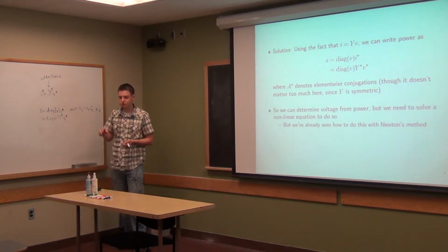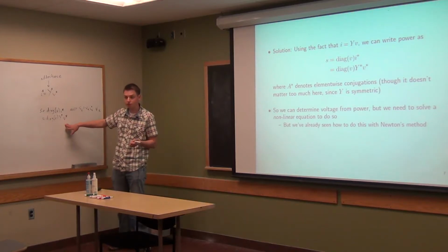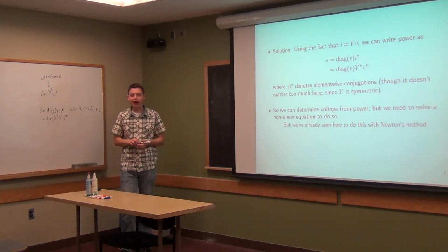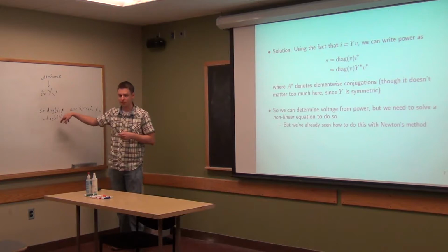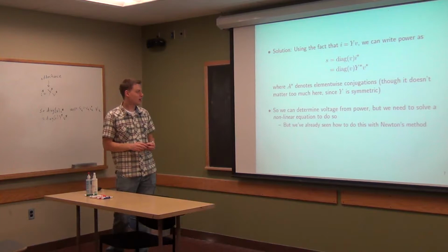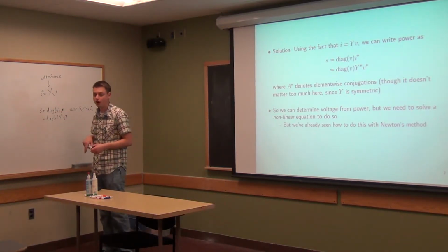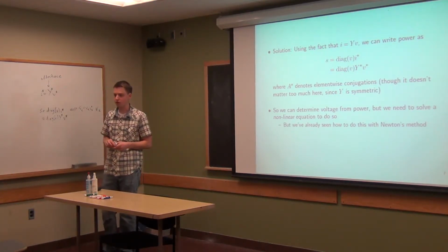Now, the nonlinearity does more than just make it harder to solve. There can be situations when it essentially has no solution, or where there are multiple solutions to it. These can all happen for nonlinear equations. But for a lot of systems, it'll actually work very well if you start from some initial reasonable guess of what these things may be. Say voltages are all constant everywhere when you first start off. And if you just then run Newton's method to solve this, then you'll end up doing pretty well. And you'll get a good solution, oftentimes.